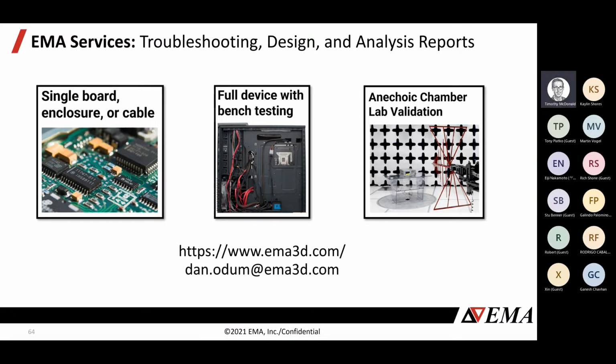Okay, there's a third option. This is a heavier project where you would like to eliminate some prototyping. You would like to go into your EMC simulation knowing you're going to pass, but you're a larger manufacturer. You need to prove out this workflow. So in this case, we're going to combine the full device simulation, like the medium offering, with some actual anechoic chamber measurements. And we're going to work with that model to make sure that we have good correlation between experiment and test.